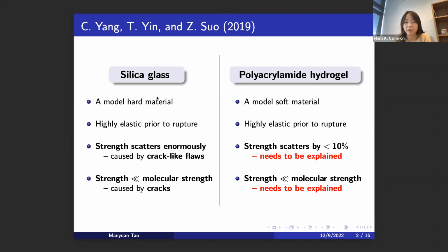They both fracture by breaking covalent bonds. However, the experimentally measured strength is typically orders of magnitude lower than the covalent bond strength. Here, the strength of a material is the maximum applied force during stretch of the material up to complete fracture, which means that the top and bottom boundaries belong to two disconnected parts.